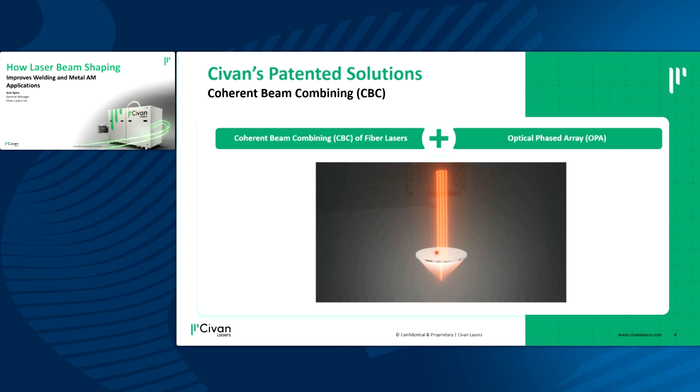The third feature is the shape sequence, which means that because we can change between beam shapes so fast, we can, in the same job, switch between several beam shapes and benefit from the different parameters or features that each beam shape has. And the same way we can steer the beam in X and Y, we can steer it in the Z axis, which is what we call focus steering, and that also has some benefits, which I will mention later. I will present a couple of slides about each of these features and go more in depth.